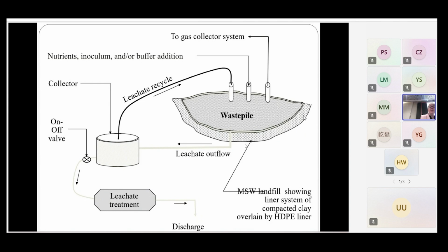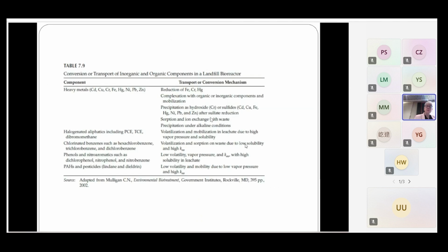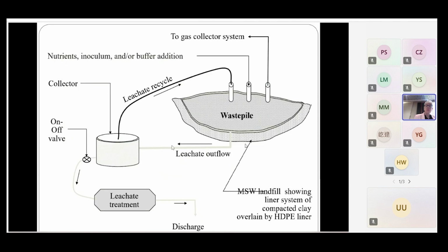But people have been looking at developing a new approach to landfills, trying to develop the landfill as a bioreactor. Normal landfills are very dry, and that's the whole aspect. What you're trying to do is keep the landfill as dry as possible. Whereas in this case, you collect the landfill leachate, and then you re-inject the leachate into the landfill so that you actually increase the moisture content of the waste in the landfill.